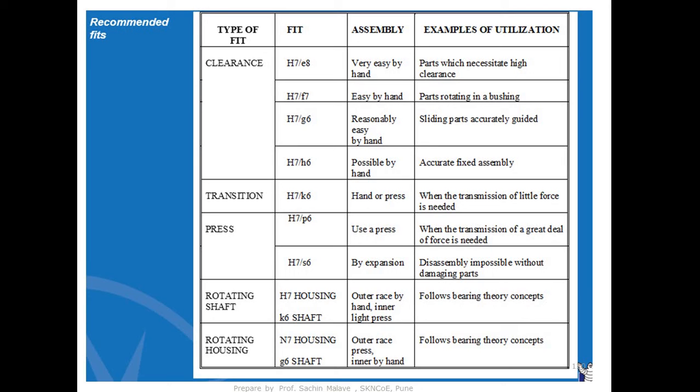So in this case, what is done here, the hole is locally heated. What happens is that due to the heat, the size of the hole will increase, it will expand for some time, and at that time you have to insert the shaft. As you insert it into this heated hole, since the size of the hole has increased, it will get easily fitted.